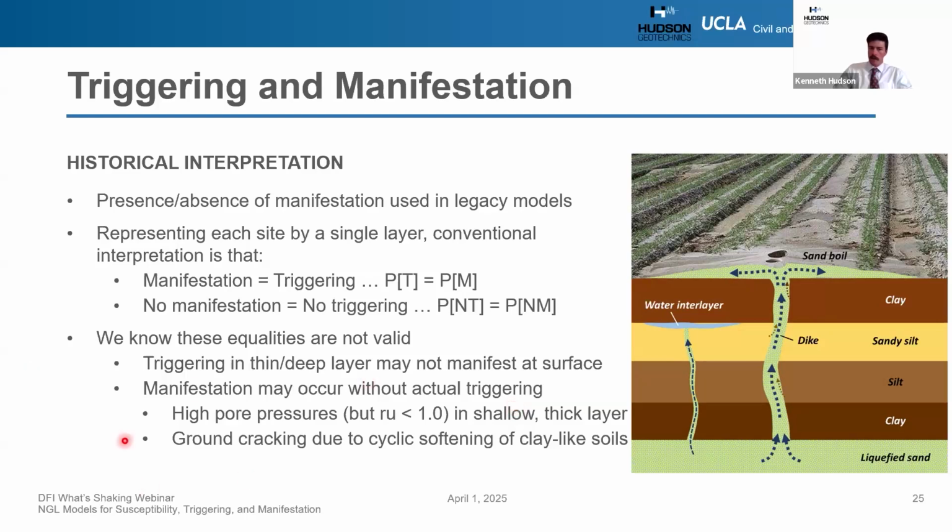We can also have manifestation occur, in rare cases, when liquefaction wasn't triggered. We've seen this happen a few times, where it was assigned as liquefaction at a site, but it actually turned out it was just some large displacements occurring from cyclic softening of a clay. We can get large pore pressures, but not fully liquefied pore pressures, in a shallow, thick layer that causes ground cracking or punching failure of footings, but it was really due to strength loss in a clay.